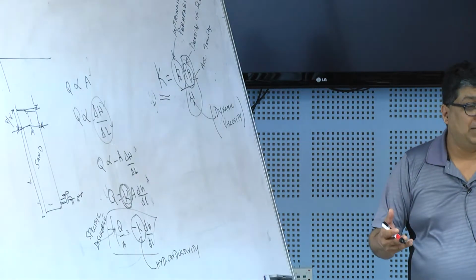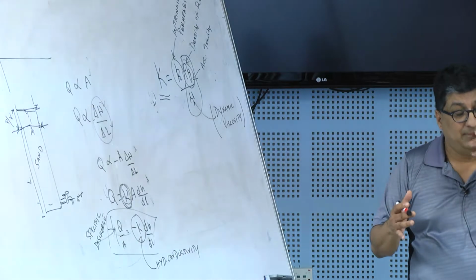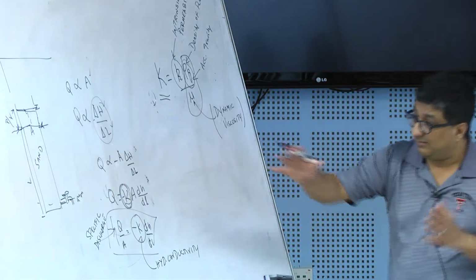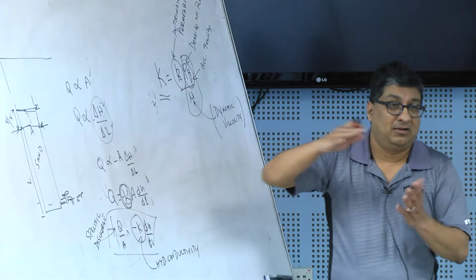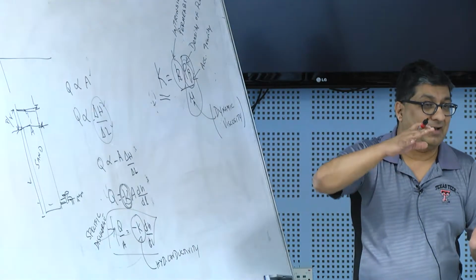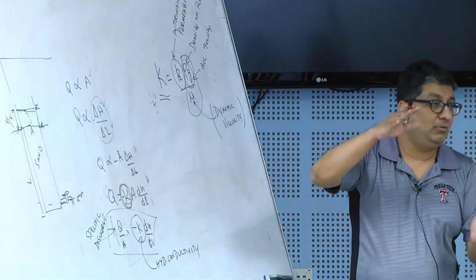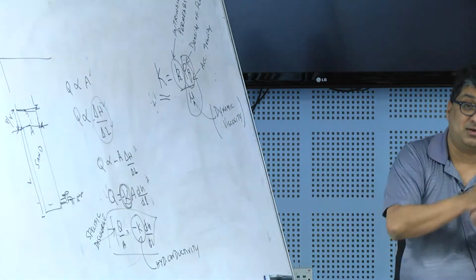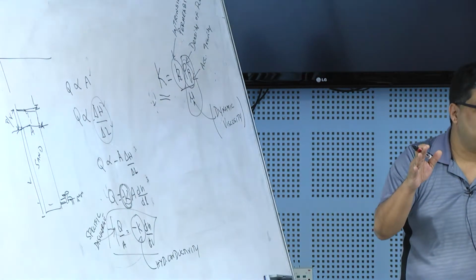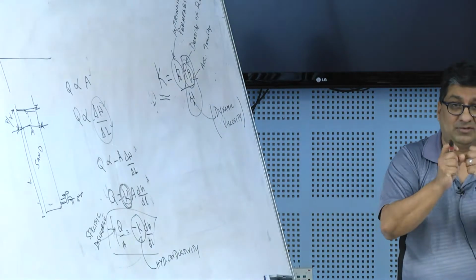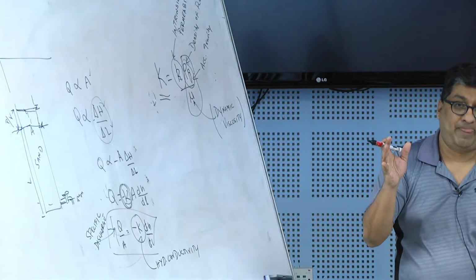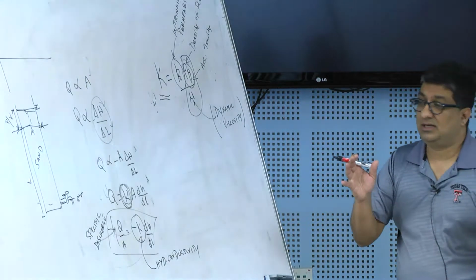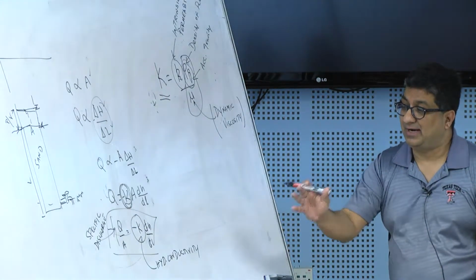But even if I take a column, a sand column, that sand column is going to have multiple pore sizes. The reason it will have multiple pore sizes is because there are multiple grain sizes, and the arrangement of those grains is what forms pores. But I have only one hydraulic conductivity value.